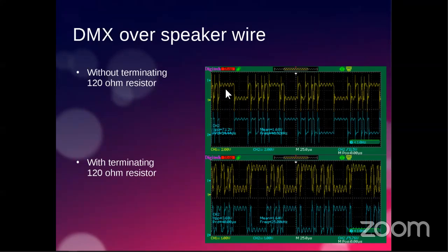There's a positive signal and a negative signal, and they actually move in different directions relative to the ground wire. And so when this wire goes high, this wire goes low. When this one goes high, this one goes low. And it's actually the difference between the 2 that is being read at the far end.